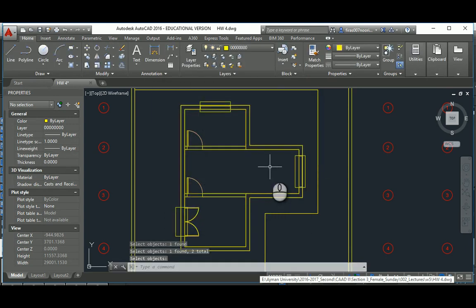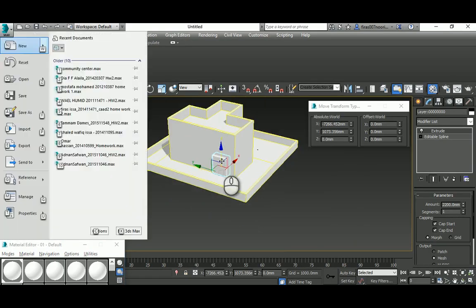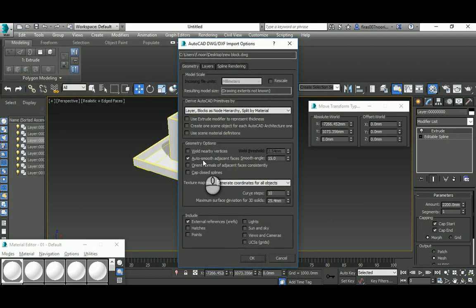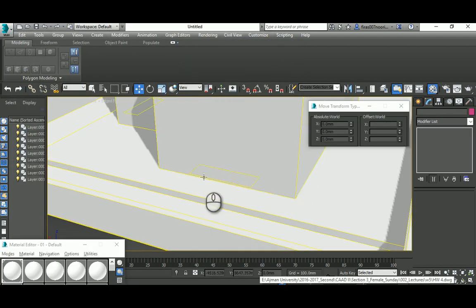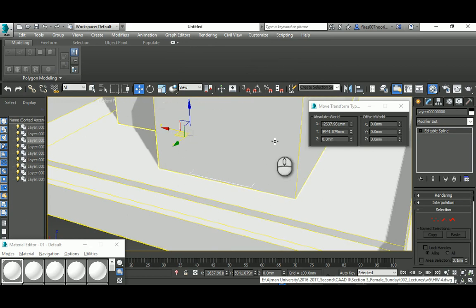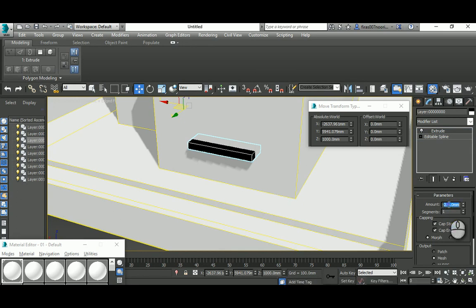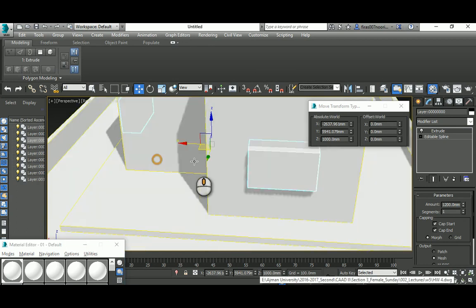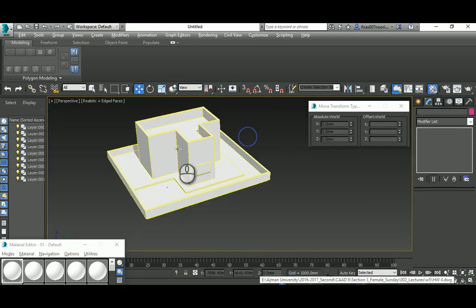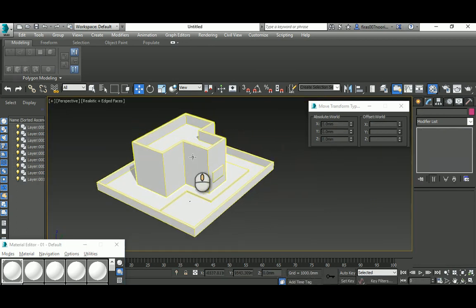And the same thing here, Alt F9, same file. A bit of a quick method, if you get practice with it. Again, from the sill I get in the AutoCAD, the height should be 1000 and the extrude should be, sorry, 1200. Add the material to it, and here we go. Now let's open those from the exterior wall.